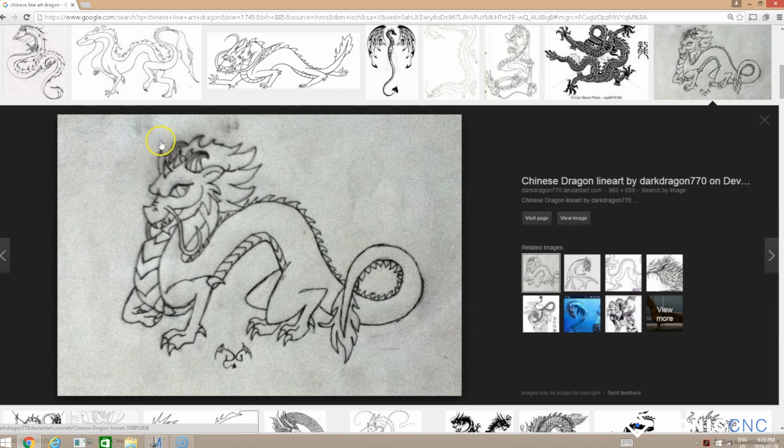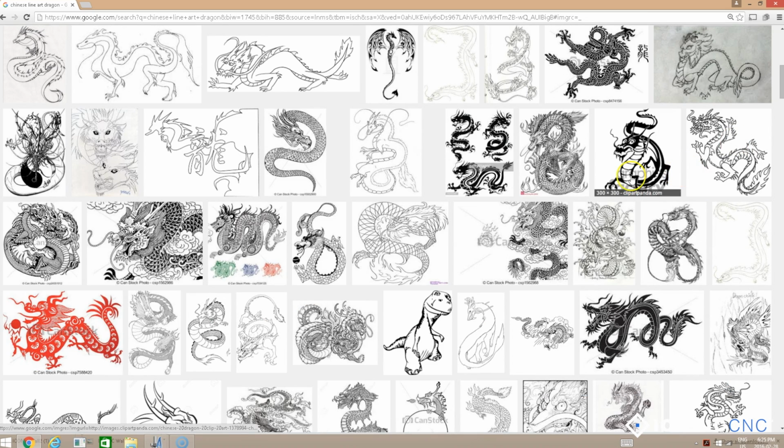So if you look at this background on this particular image, you can see that it's got these changes in shading, and that's going to be problematic, because what the software is going to do is it's going to trace around this image to try to establish basically where to create machining toolpath. And if you've got all of these changes in shading, that can be a problem, because it can't really determine where to kind of draw the line, if you will.